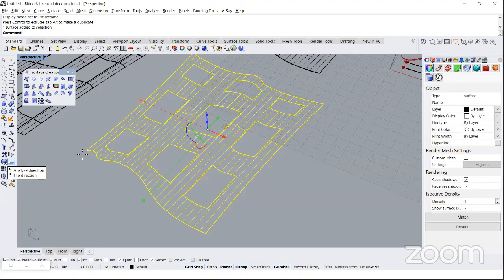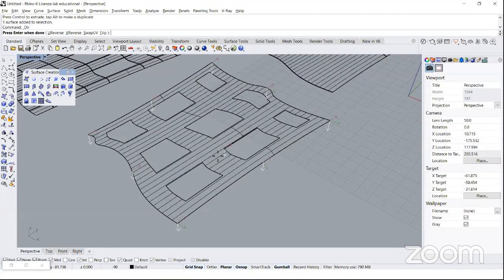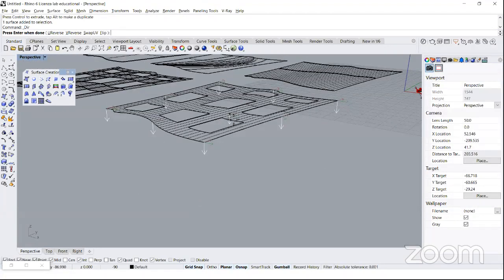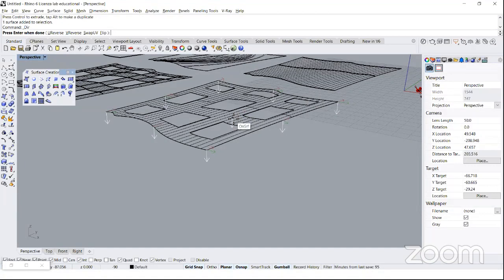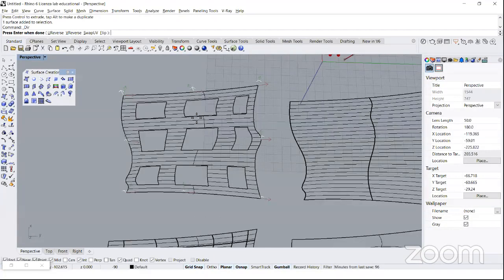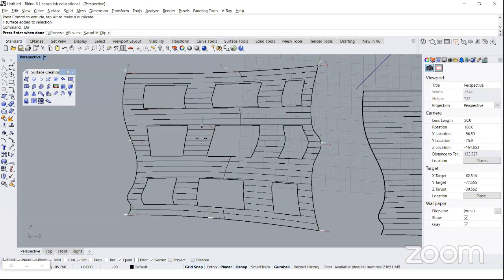So left click. Now, what we see here is the actual parametric coordinate system of this surface, the famous UVW coordinate system. And you see that the white arrow, which corresponds to the W, which is the positive normal direction for this surface, is pointing downward. This is what makes this surface look downward. So that's why we see orange from the top side. Now, if I go and place myself on the tip of the white arrow, so I am actually looking at the surface from its positive normal direction, okay?